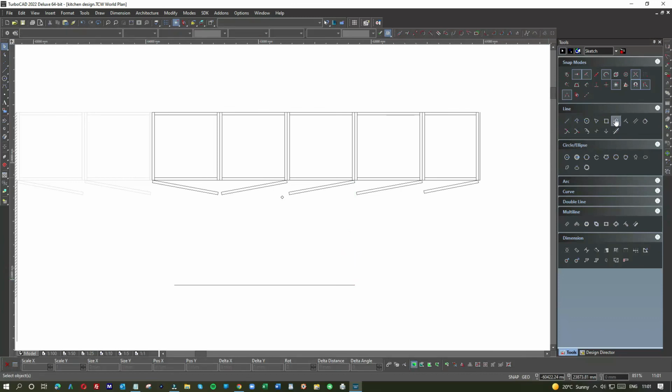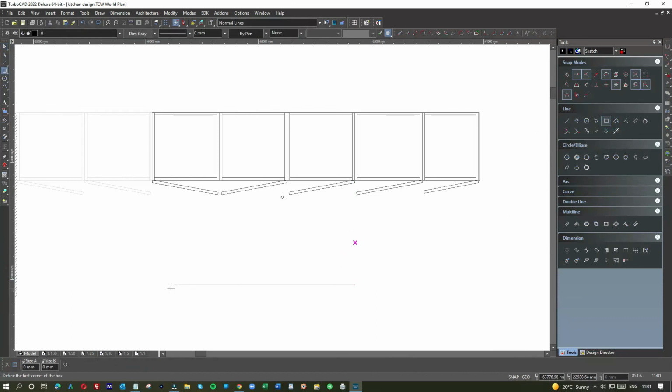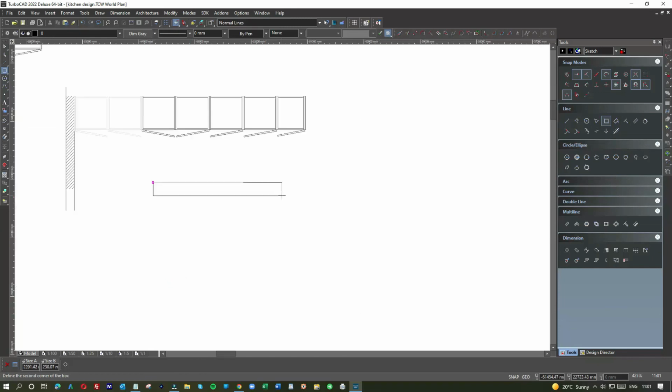So if I was doing it, let's do that, and then what about the depth? Well, let's face it, 650 will be if we just want to cover a range of units like here. 900 if you want a bit of breakfast bar. So let's just do 900. So we tab down.